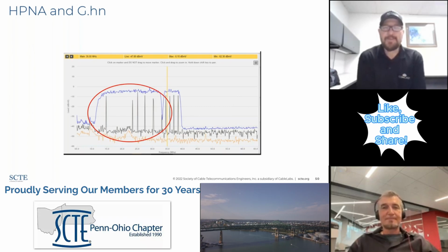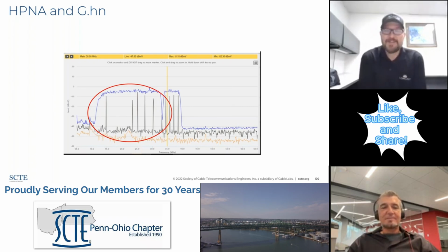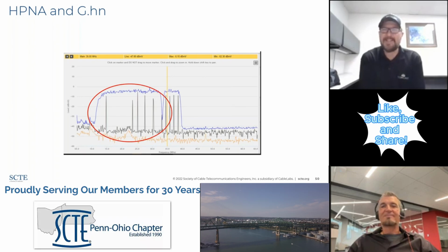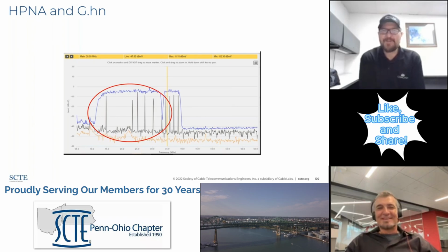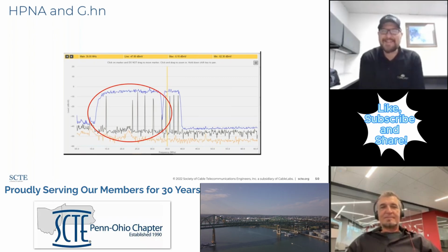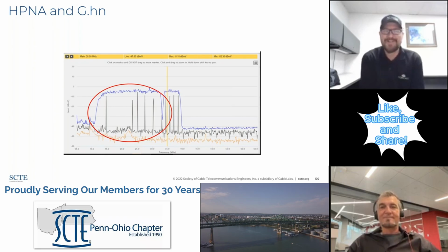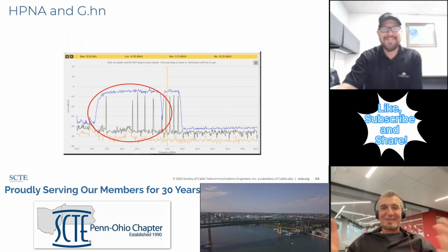Yeah. So irony of ironies, at the beginning of the broadcast, we talked about the differences between DOCSIS over coax versus the fiber-based providers. But the irony here is that fiber-based providers actually use RF over coax inside the home. So when we're not properly isolated from those fiber-based providers that are using coax and RF to communicate inside their premises, that can actually make its way back onto the coax network from the DOCSIS providers. Well, they're just being opportunists, right, Mike? There's a perfectly good coax sitting there between rooms. Why not use it? That's right.